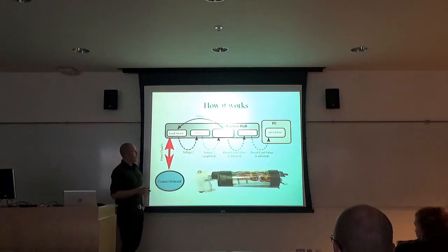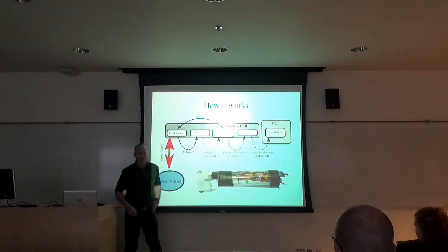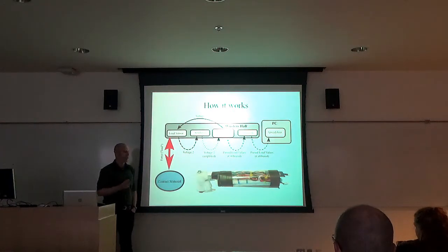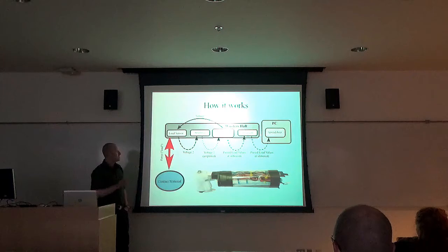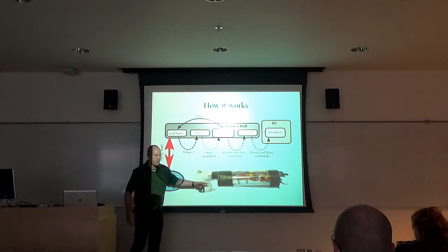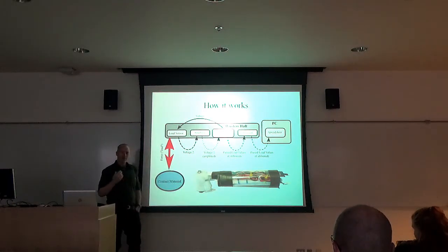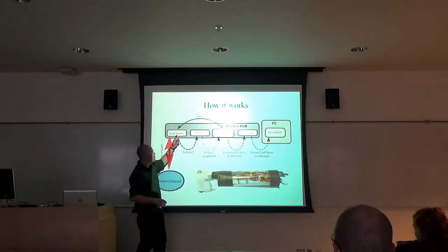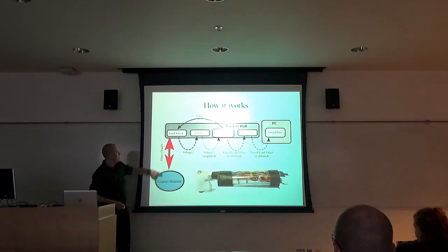So the way it works is all based on this. It's a microcontroller. It's a little circuit board called a Teensy, and that's the brains of the operation. It holds the code and controls the data and does everything. And that Teensy is paired with a load cell. The load cell is this aluminum bar here with a couple holes drilled through it. The aluminum bar has resistors bonded to it, and so the Teensy sends voltage through those resistors. When there is force being applied, when there's a load, that bar deforms very slightly, and the resistors deform very slightly, and that voltage changes.